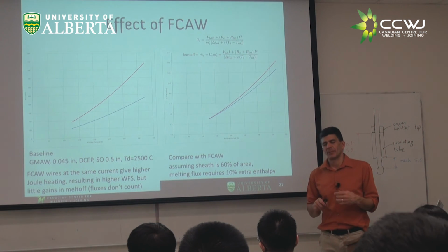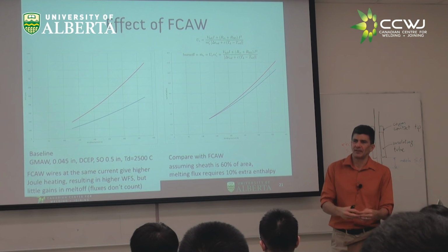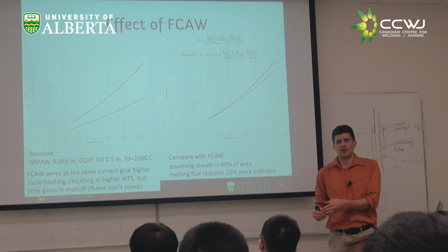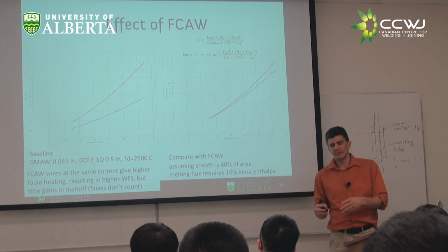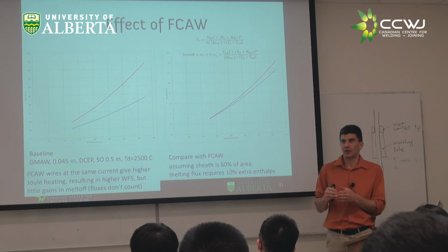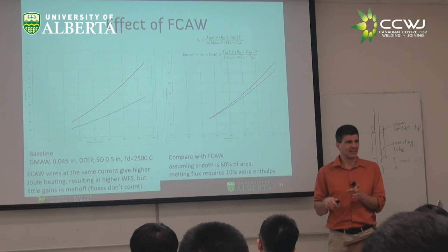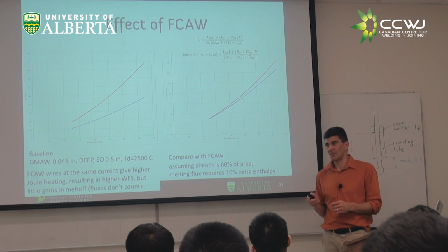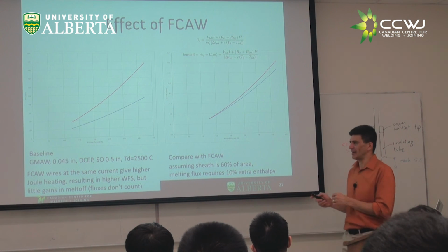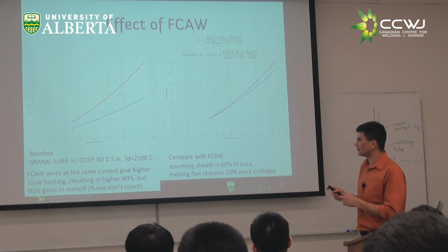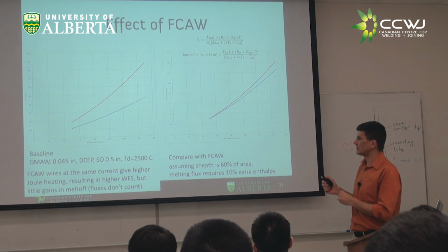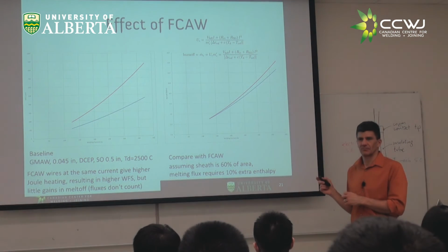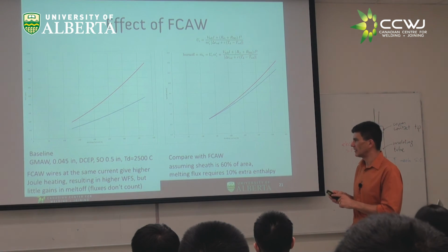So they can sell me flux core for the productivity. They cannot sell me flux core for the deposition rate. Now, flux core compared with MIG is kind of meh, but flux core compared to stick is awesome, right? And the competitor of flux core is not MIG, it's stick. And flux core is amazing, right? Don't do stick. That's the bottom line. Okay, so this is what I wanted to show you about deposition rate, and how to calculate it.